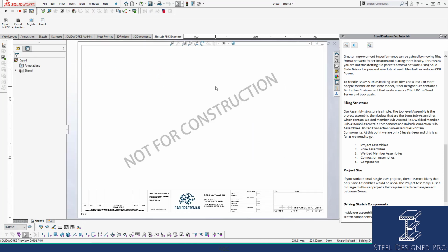Now this is a sheet template. That's different to a drawing template. Sheet templates hold the data and they hold all the lines for your borders. Realistically, this is your sheet template data. Okay, and sorry, they're your hole anchors, I should say, and then there's a border that comes with SolidWorks. Typically I usually delete that. You can leave it in there, but I typically delete it myself.